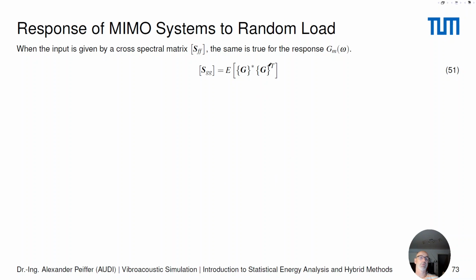So we write the output in this form, as was shown before. That's why we're using this famous vector form. And now we write each component of this product in the matrix form. So this is the complex response with the response function and the force. And if we transpose, this changes the order. So we have the transpose force vector here and the H matrix on the right-hand side, and we just put this into this equation.